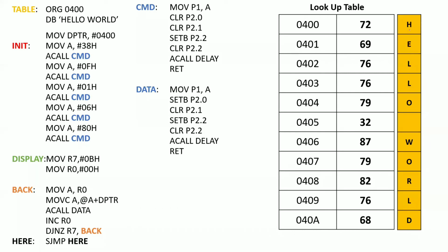So that's why I'm going to store the HELLO, and there is a space also there, and WORLD. Okay, sir, can I send H directly to the LCD? No, no way, right? So that's what I need to do. I need to convert that H to ASCII value. Each and every character, special character or digit has an ASCII value. That ASCII value will be stored inside the memory location, right? For H it is 72, for E it is 69, for L it is 76, etc.